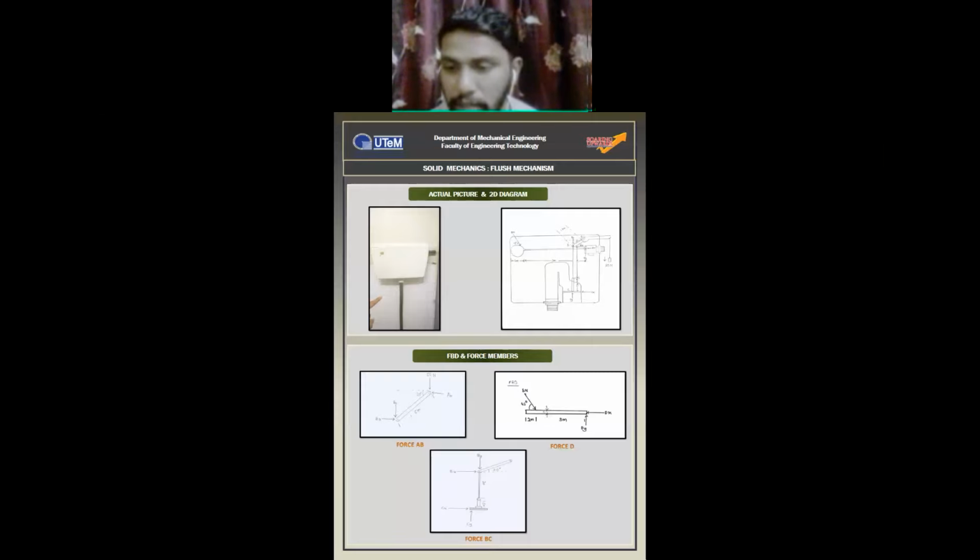Then this provides suction in the siphon and the rest of the water within the siphon U-tube flows. The piston is usually covered by a plastic membrane, which is sucked out of the way by the emptying siphon tube water, allowing the rest of the water in the tank to rush past the piston and over the top of the siphon, emptying the rest of the tank. After that, the piston membrane drops back onto the piston, ready for the next flush operation.